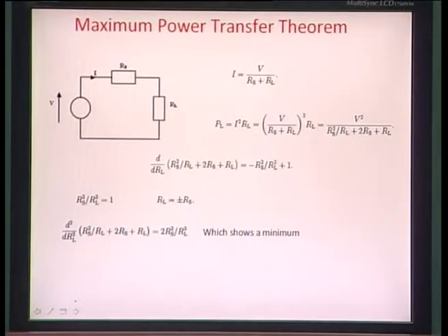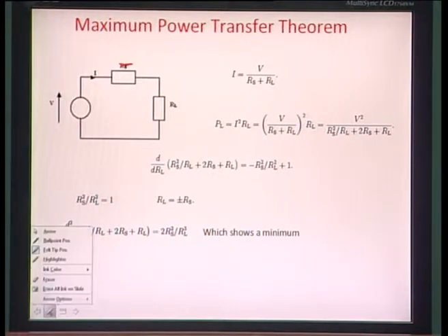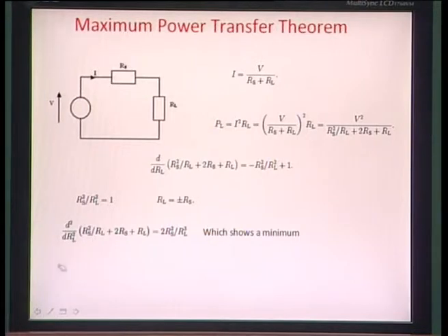It states that if you have a closed circuit with two resistance or impedance values, as you are seeing, RS and RL, where RL is the load resistance and RS is the internal or source resistance, and you apply a voltage V across these two elements, thus generating a current I in the circuit. For maximum power transfer from this voltage source V onto the load resistance, the condition that you have to meet is basically an equality between the source resistance and the load resistance.